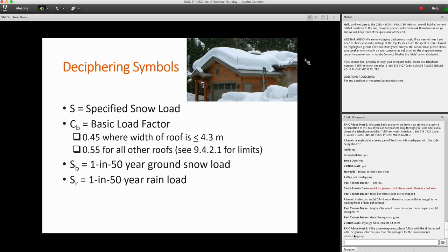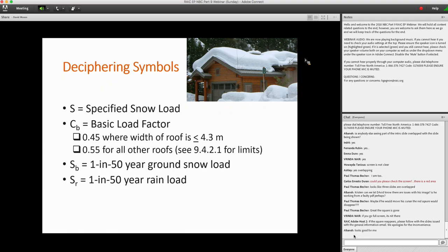One of the interesting things in our building code when it comes to snow is that historically in Canada, the failures that have been observed on roofs due to snow are typically in Part 4 buildings, and not necessarily in Part 9 buildings. And so statistically, the writers of the code have looked back and said, well, typically Part 9 buildings have a lot of repetitive members, they're closely spaced, the buildings are only a certain size, the effects of additional snow drifting, even the effects of snow, we just haven't seen the types of failures or the number of failures due to snow. So because it's less common, they've reduced the basic factor.